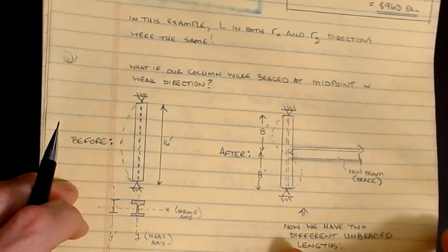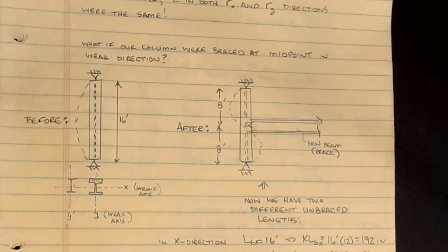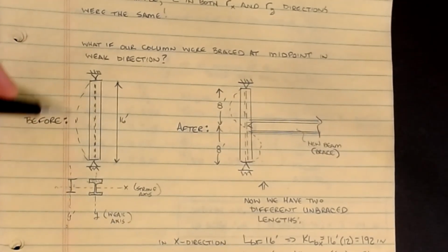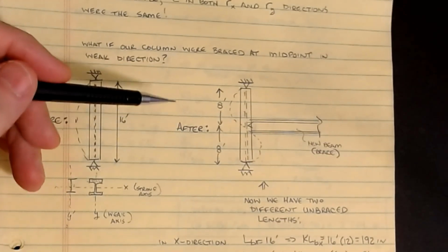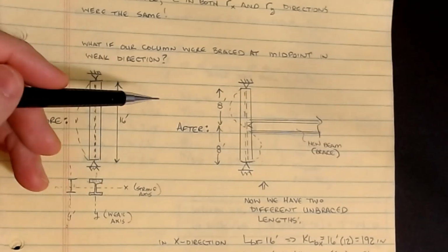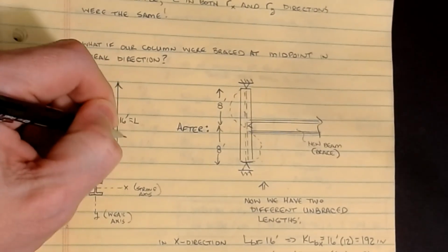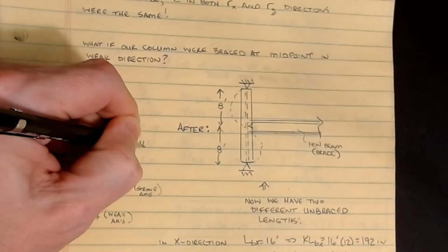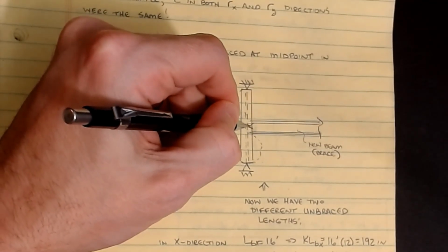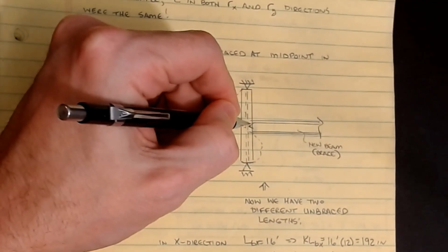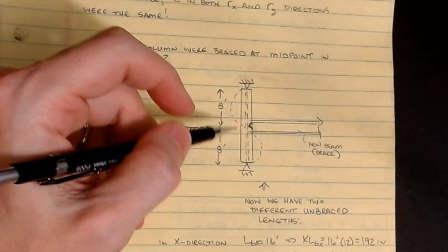Okay, so one of the tricks that we do in structural design is that when I have a y-axis beam that is experiencing a failure, that it's controlling, sometimes I will provide some bracing into this column in order to reduce the length. So here, this was my L value, right? And KL here was 16 feet. Okay, now if we put a beam in the mid height of this and assume that it is able to establish a pin connection there, through some connection of the web.